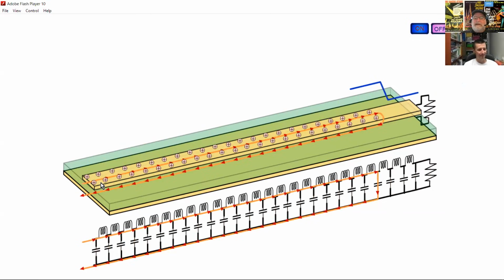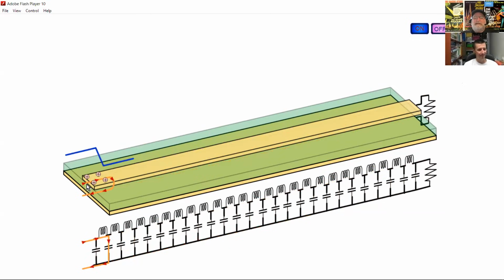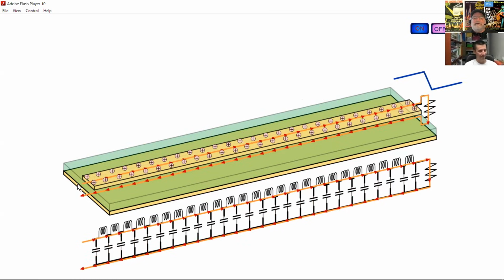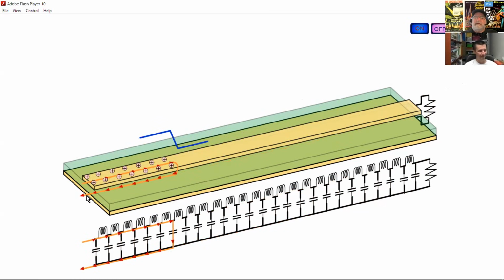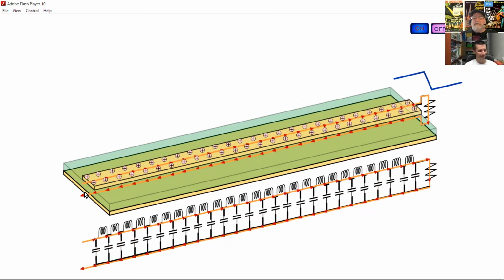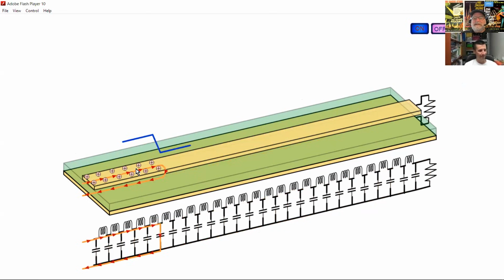And so that says that right at this very instant when I'm beginning, just when it launches, look at the beginning, I don't know where that edge is. All I know is I have signal going in, I have signal coming back. All I know is there's 50 ohms looking in for as long as that signal is propagating. That's why a transmission line, when we look at the instantaneous impedance that signal sees, it doesn't care what's happening at the end until it gets there.